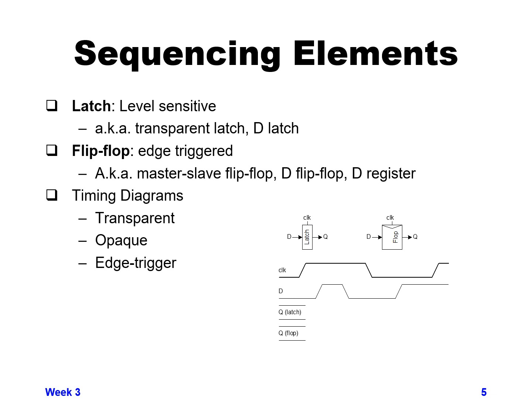And this allows a signal, input data signal D, to get captured and go out to Q when the edge of the clock switches between 0 and 1. So as the clock switches from 0 to 1, at that instant in time it captures the value of D and sends it out to Q.